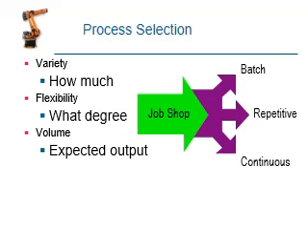So this is job shop production. But in batch production, if you consider a bike, we already have a standard set of facilities available. All the cells are available, and all the cells are manufacturing standard components. We are manufacturing in different cells and bringing them from the cells to assembly. This is batch production. Another one is repetitive production, where we repetitively manufacture the components.